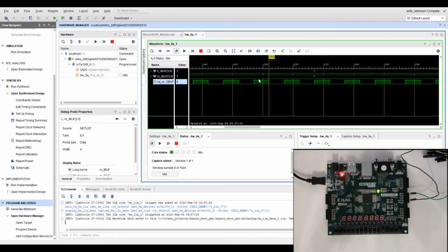And the answer is yes, it's still 100 nanosecond, but the clock is operational at 10 nanosecond, and this particular window is triggered every 10 nanosecond. So everything you see in here, it's actually not in the 10 nanosecond, it's actually between here and here. Every move you see is actually 10 nanoseconds. So from here to here, the difference is actually 10. You multiply by 10 and you get the exact nanosecond.